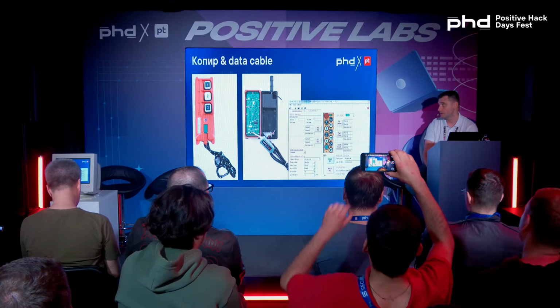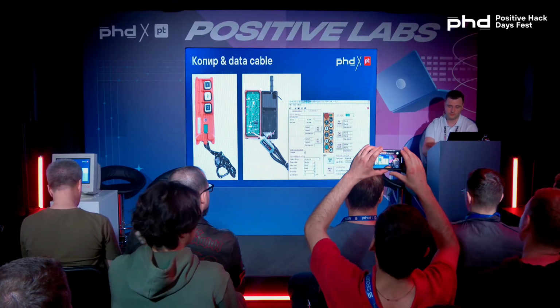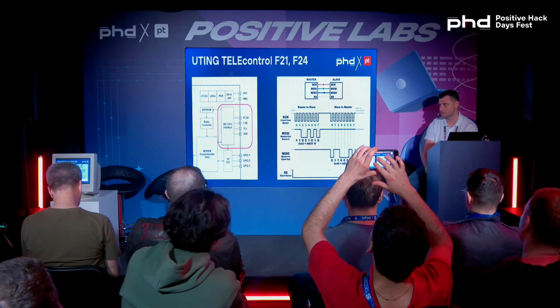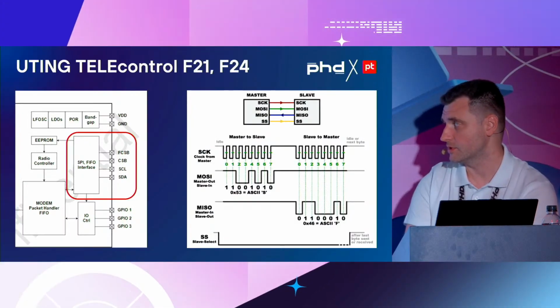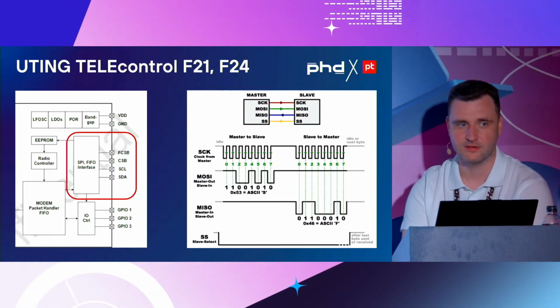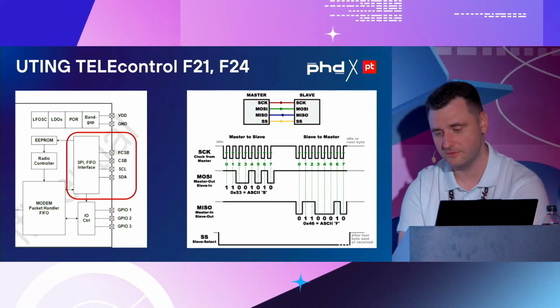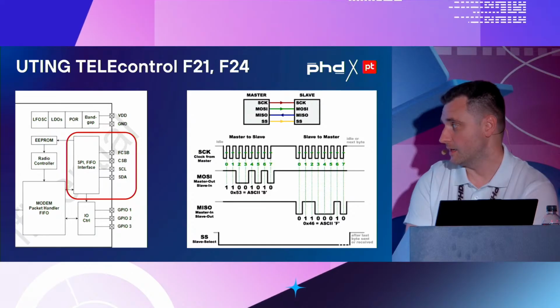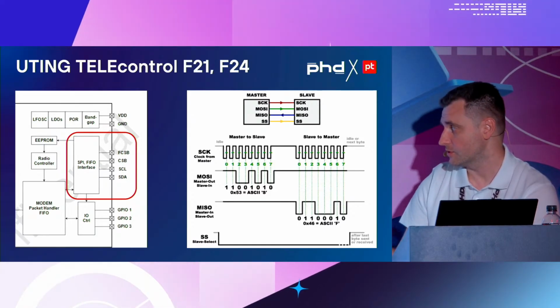We got interested in how the information exchange looks between the receiver and transmitter. We could have made an SDR radio to analyze that and guess something, but this is just a simple SPI. You can connect it to a logic analyzer and get the data in a guaranteed way. This is what we did.